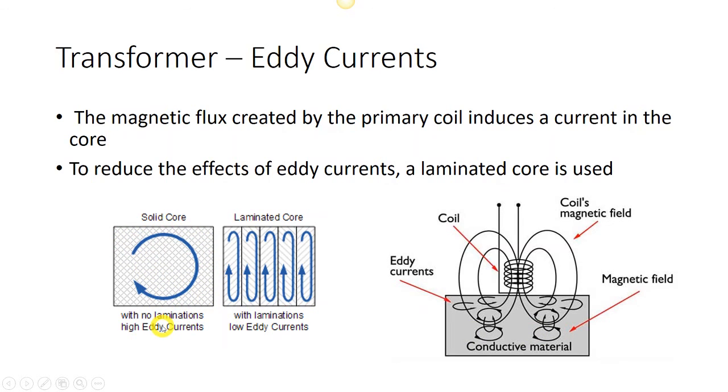And so when you look at the transformers in lab, you'll notice that the soft iron core is actually a whole bunch of steel plates stuck together. And so they're laminated as well, so there's physically no electrical connection between one lamination to another, and that is a physical barrier to keep these eddy currents extremely small, and that keeps that eddy current loss extremely small as well.